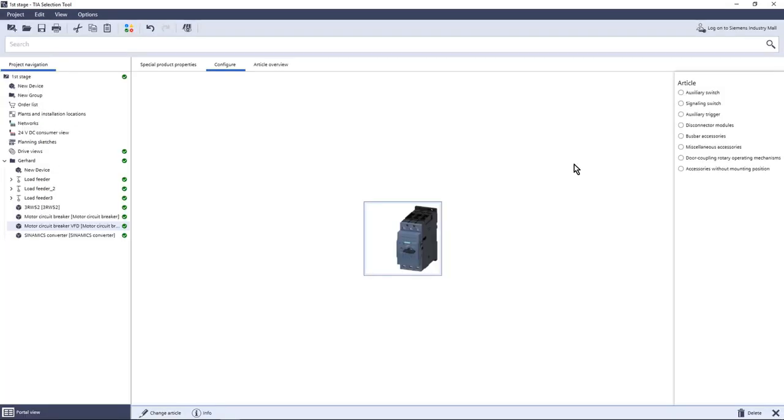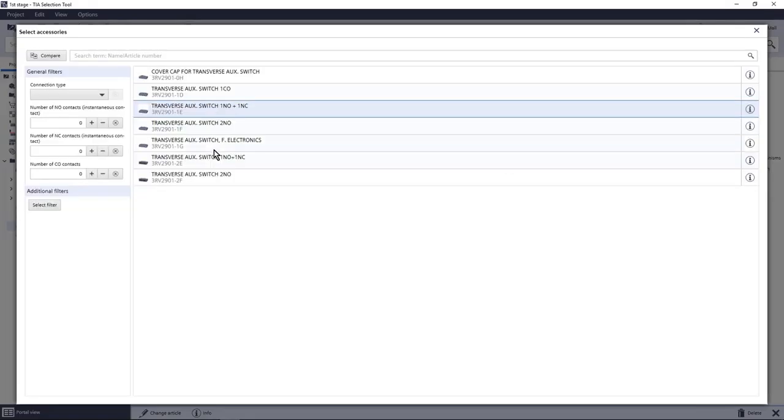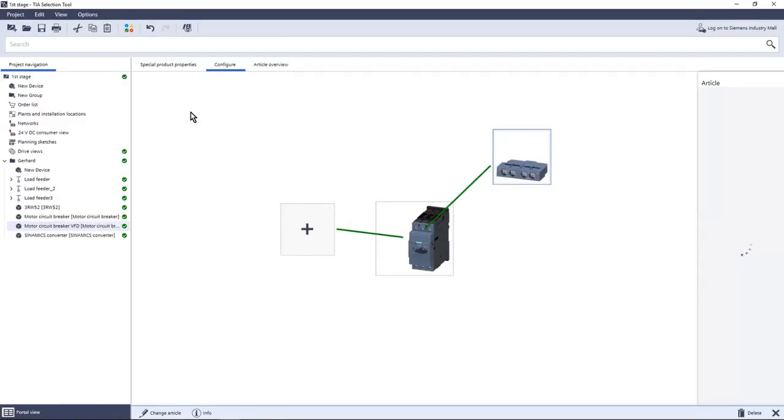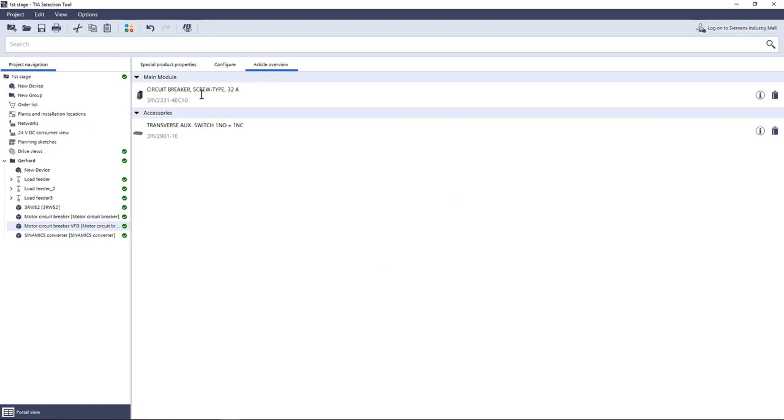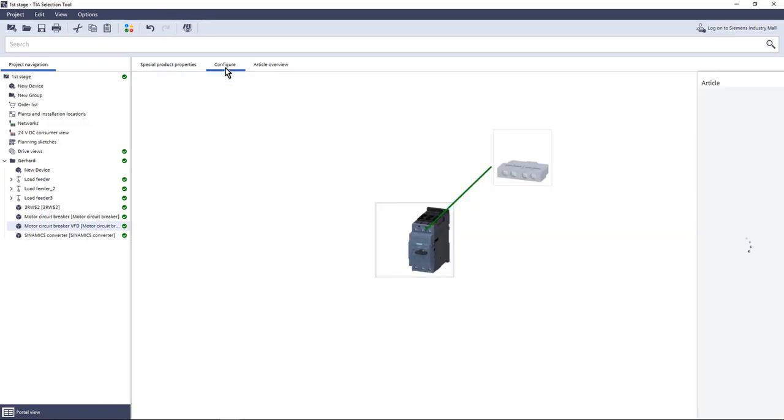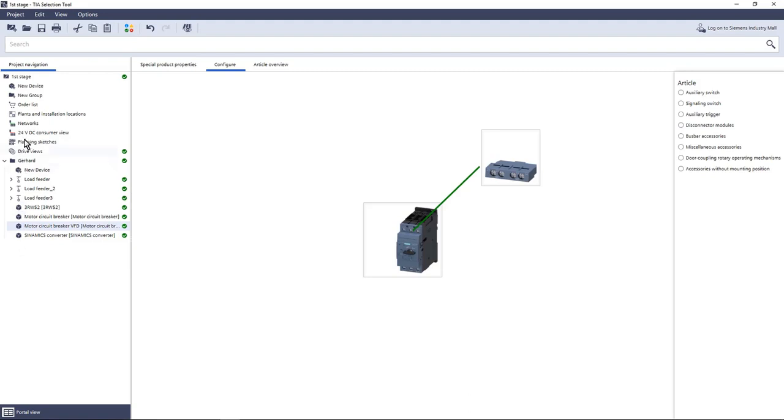And after I delete this, I can either select it by operating power or by amperage rating. I go for the 15 kilowatt. Remember, we're still using starter combinations. So basically all of the MSPs that are coming here are only magnetic. So as you can see, it gives us an operating current of 32 amperes. The drive was with 31 amperes, so it's a really good selection that we have done here. And basically now we can end with it and we just close it.